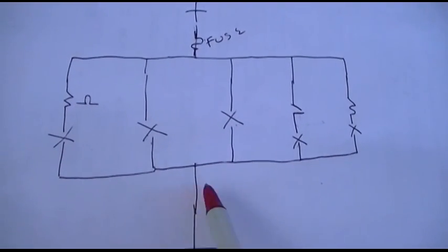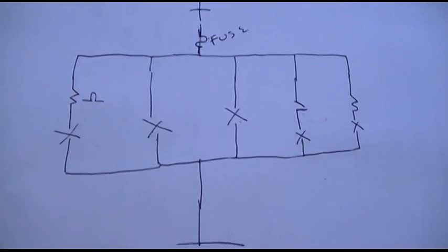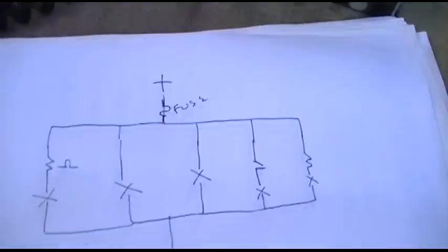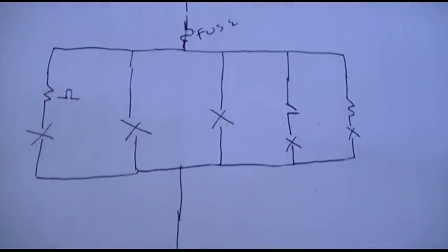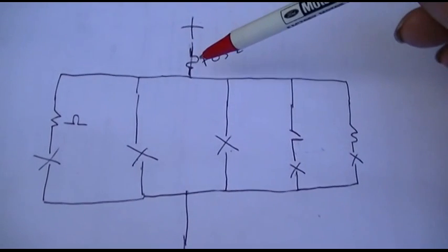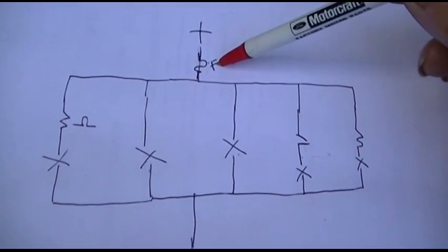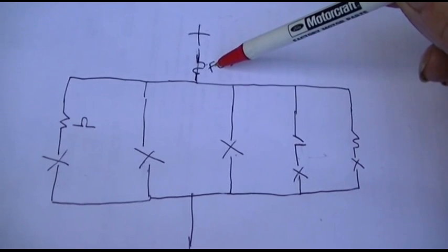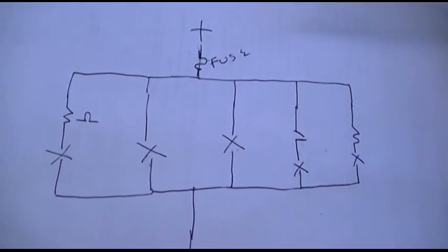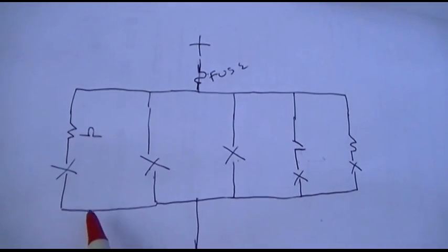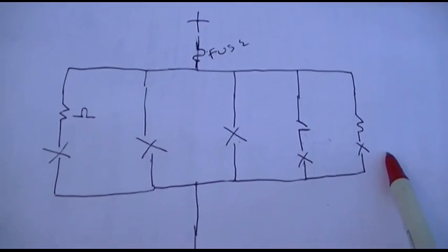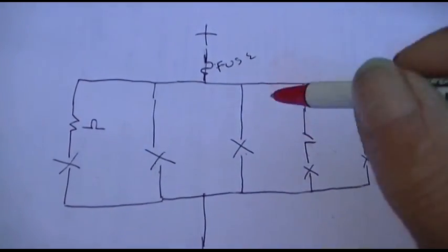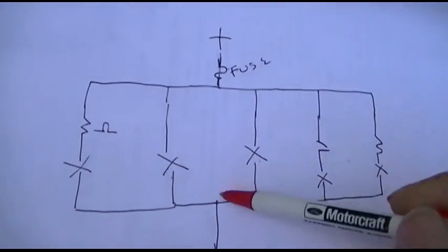Let's say it's a tube radio, or this radio, because that would be the same. You have your fuse, or let's say this is the rectifier right here, and it's turning blue and burning up the rectifier tube. You can look at the schematic and you can see some of the loads are going to be direct. Like for instance, the filter capacitor would be direct.